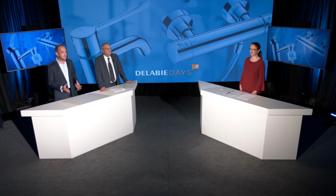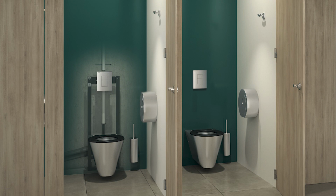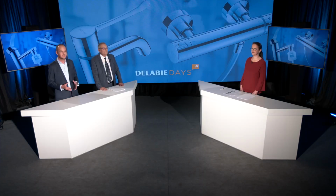To support this, a study recently published in the French Hygiene magazine revealed that Legionella can develop very easily in the toilet cistern. It actually developed in some hospitals via their toilets. So at Delabie, we have an excellent technical solution to deal with this problem. It's called a direct flush valve, and it works without a cistern. So with no cistern, there is no stagnation. The water does not come into contact with air before flushing, so there is no risk of bacterial development at this level. Many hospitals have already opted for a direct flush system without a cistern, and this trend continues rapidly.